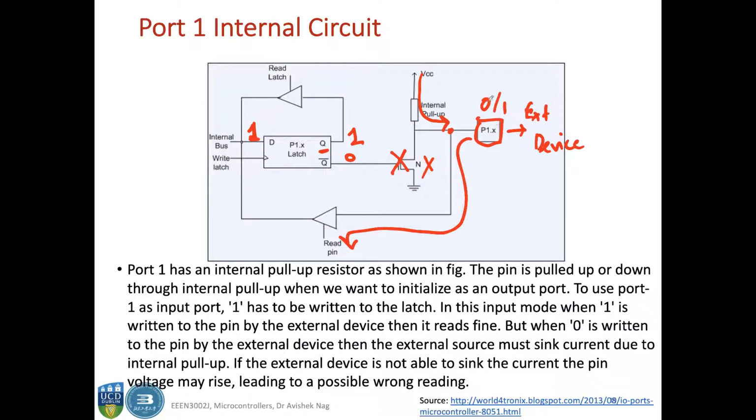However, putting a 0 here should be done with a bit of caution, because when 0 is here and VCC is here, there is a significant potential difference between this point and this point. So there is a chance that this external device will start drawing current from this VCC because it's a 0.